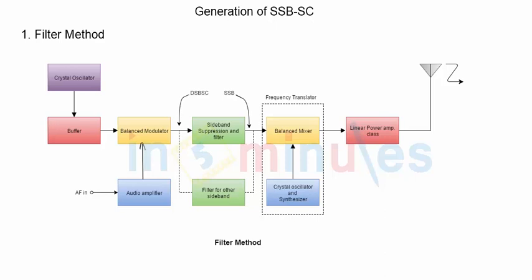So this very simple and smart modification in the design is done so that we don't have to design the filter to operate at high carrier frequency. I repeat, in this new modification, you design the double sideband suppressed carrier signal at low frequency first. You remove one of the two sidebands at low frequency only, and then you perform frequency up conversion. You send the remaining sideband, which is present at low carrier frequency, to the final high carrier frequency and then transmit it. So let's see how the block diagram would look.